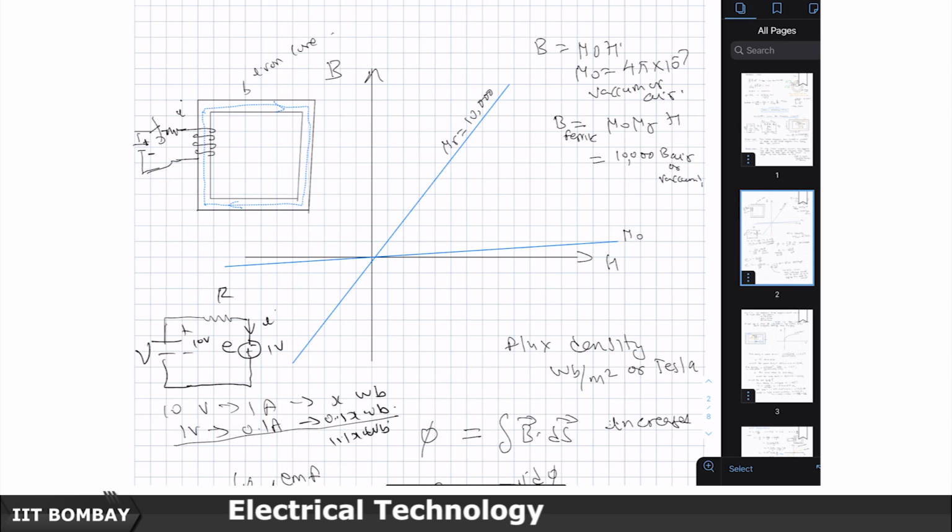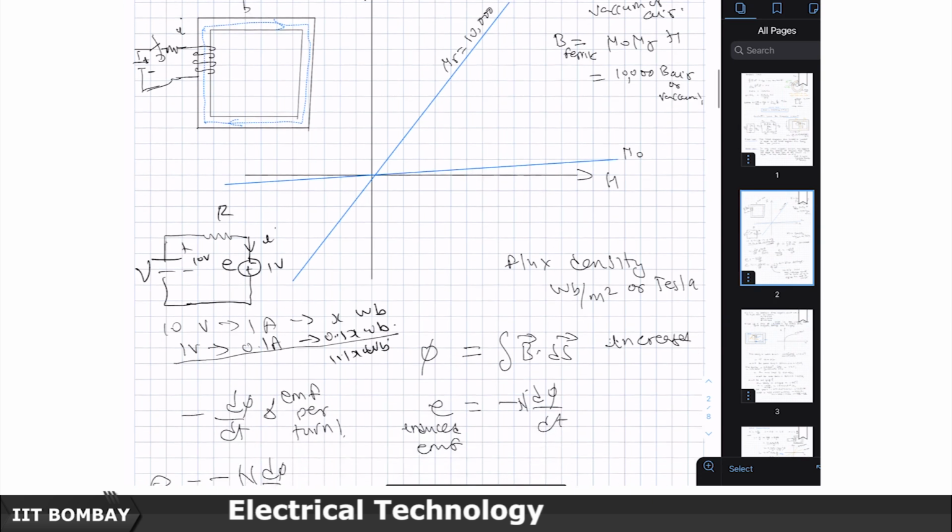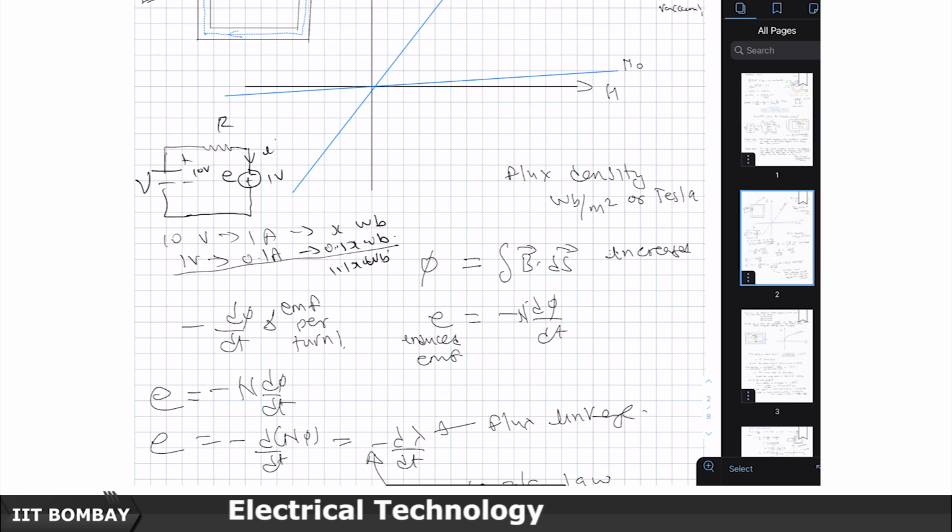So, what the Lenz law says is that the induced EMF has to be in such a way so as to oppose this change, and therefore, if this is the convention which I have used for induced EMF, then actually the voltages should be the other way round, and not trying to increase, but it should actually lead to minus 1 volts so that the net voltage will tend to oppose it, and to get this minus volts here, we just introduce this negative sign here.